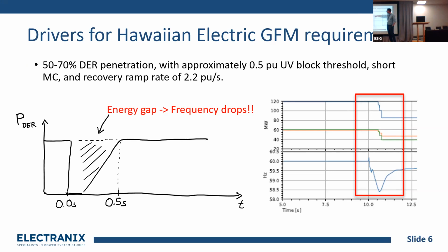So looking at this power out of the DER, what can happen, and we don't even really know for sure that this does happen, since we have very little hard data on what a really large distributed energy plant or system looks like. But for now, let's say we have a good guess that when we go below a certain voltage during a fault, the active power is going to go to 0 because it'll block.